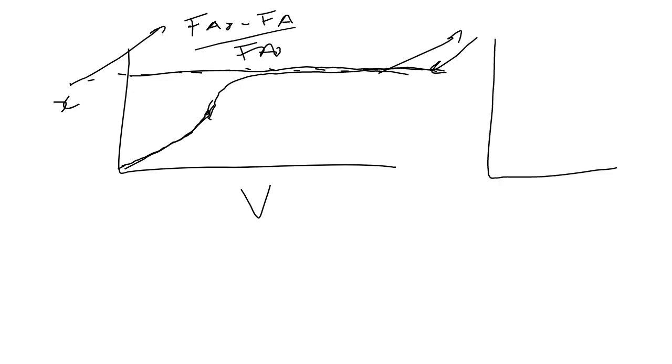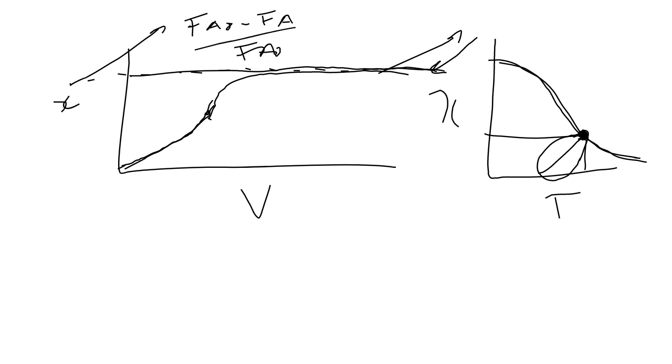So this line X_T should correspond, if you did everything correctly, to whatever you calculated there by solving simultaneously for your adiabatic energy balance and your X equilibrium line. So for a very large volume, this is just what you are going to get. Now let's say you go to that maximum that you can find, and now I cool it down.